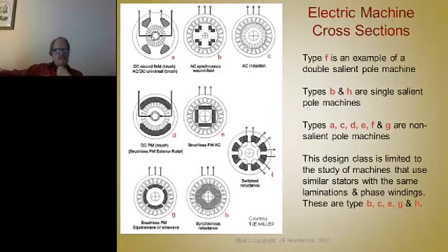But these DC motors evolved into synchronous motors. Remember, that was our second motor. It was an AC synchronous motor. It is a wound field on the rotor, much like the wound field on the stator of a DC machine. So this rotor produces DC current flows in these coils, producing north-south poles, and then the flux from those electromagnet poles in the rotor link with the conductors in the stator, so you have a synchronous motor.